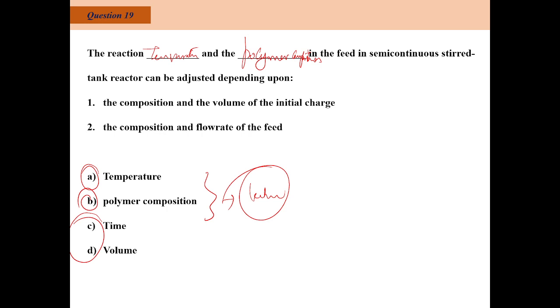Whereas here I am talking about some polymer where I look for a very wide molecular weight distribution. Say I will have a polymer with a number average of 1,000, and it can go up to as high as 1 lakh. That is specifically tailored to meet the end use requirement. After this, the polymer is going for some other application as a binder. So there I need this much wide distribution so that the final properties of that material, like a composite material, will have the advantage. So there I go for batch.